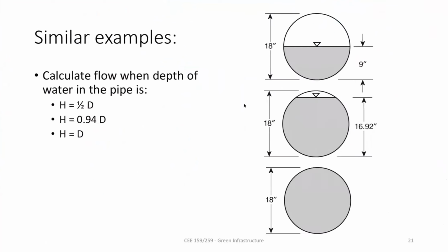The force is 1/2 times h, where h is the height of water, times rho g. This is the density of water times gravity, and this is the height again. B is the width of that wall over here. So for a vertical wall, that's the force.